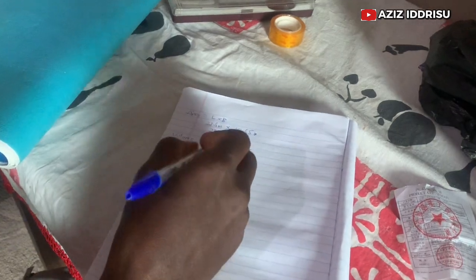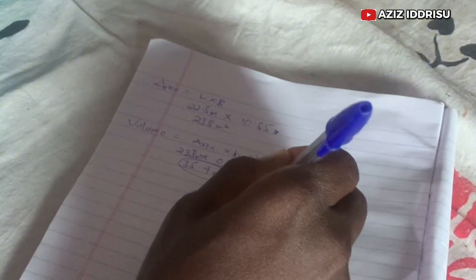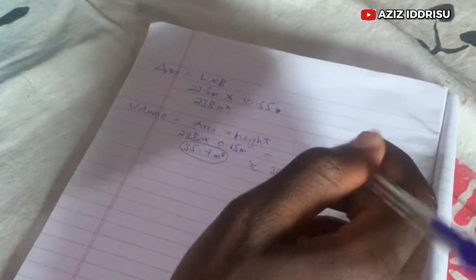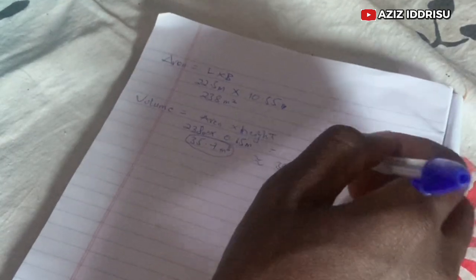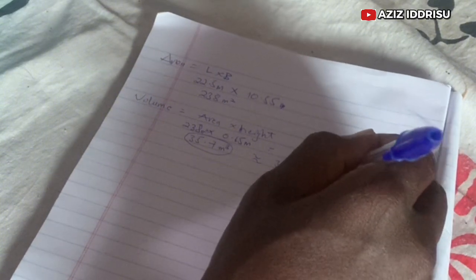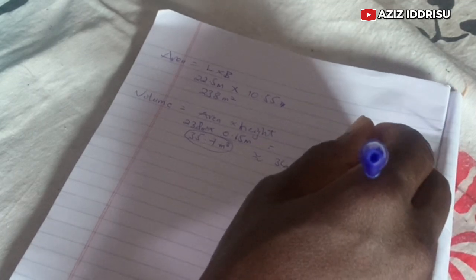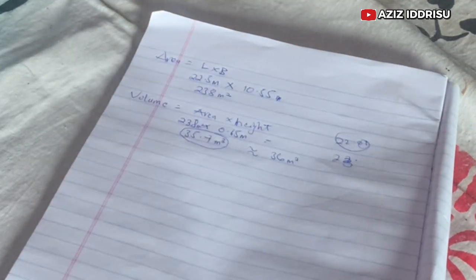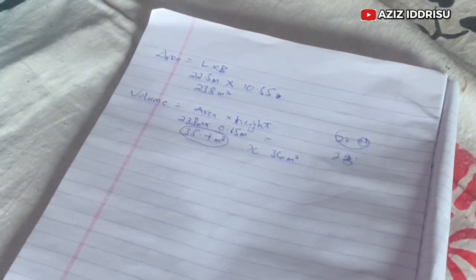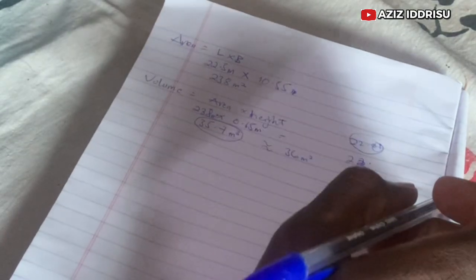So we'll be working with this volume now, 35.7 cubic. So we can approximate it to 36 cubic meter. Now in construction or in quantities, even if it's 22.01, we don't approximate it to 22, but rather 22.23. Because if you forget about this 0.01, it means your materials won't reach, and it's better for it to be more than enough than it not being enough to finish the project.